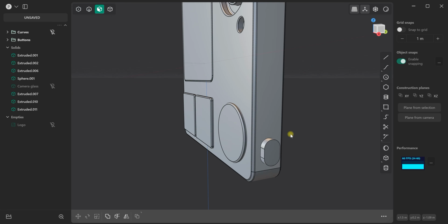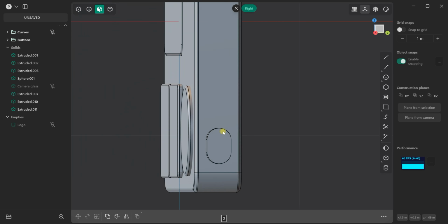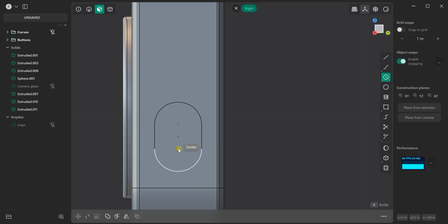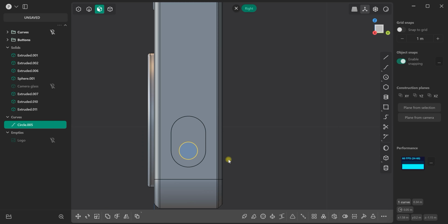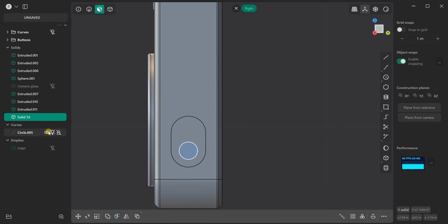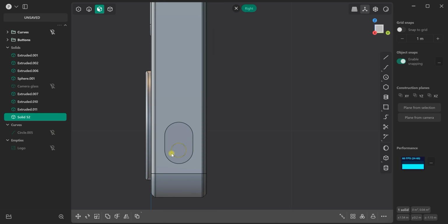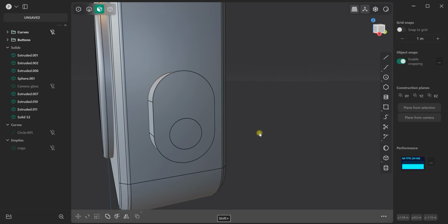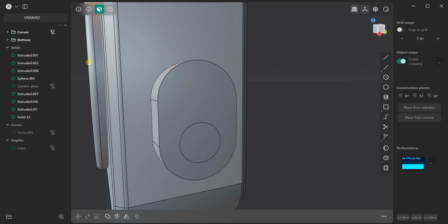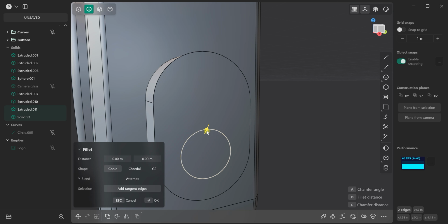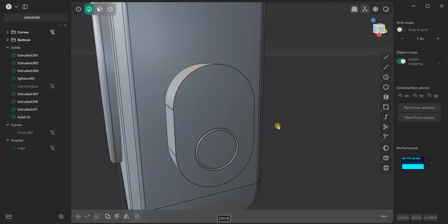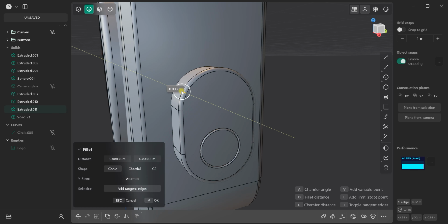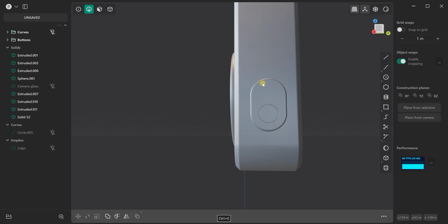Let's create a circle here, and now we're gonna cut it. Let's create circle. Yes, press C, click our mesh. OK to confirm. Now we've got 2 separate parts. In edge mode, select our lines by holding Shift. OK, and give nice fillets here as well. And here as well. Something like that.